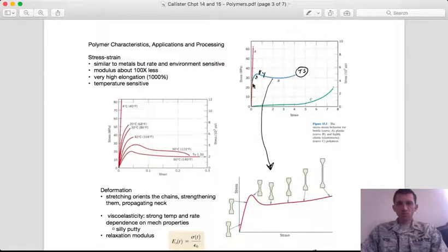They're more brittle with higher molecular weight and various side groups. You can make a material stiffer and more brittle. You also have more traditional tensile behavior here, albeit at lower stresses, where you would have an elastic region, a yield point, significant plastic deformation, and then fracture.